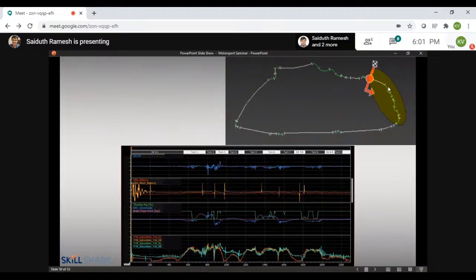You see the first set of corners here. You go flying down here. You can see how the aero balance and mechanical balance changes. You can see how the tire saturation changes. You see spikes. The tire saturation goes up too much, you'll start losing end on that end of the car, losing grip. I'll just flow through this quickly.